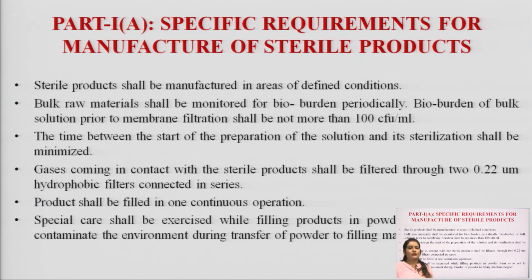Gases coming in contact with the sterile product shall be filtered through 0.22 micrometer hydrophobic filters connected in series. The filters must be connected in series. So, whatever the gas is going to be used, it should be free from microorganisms.